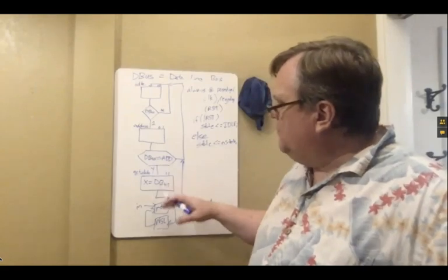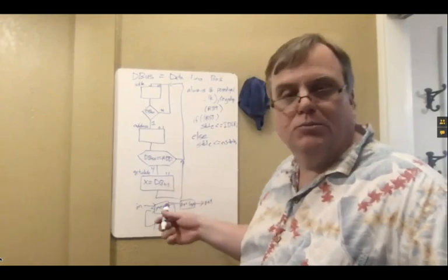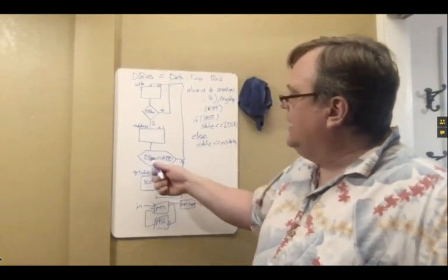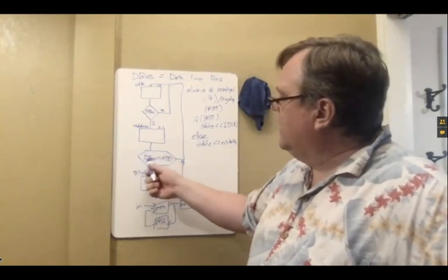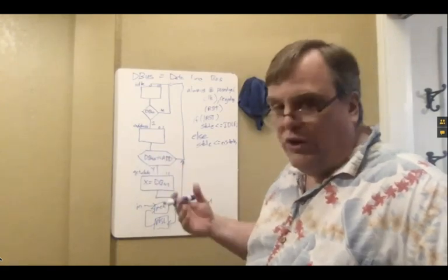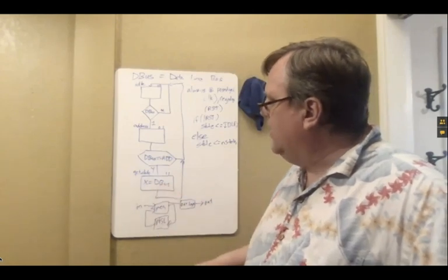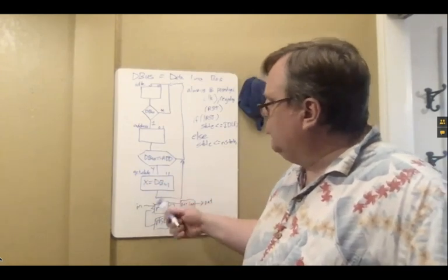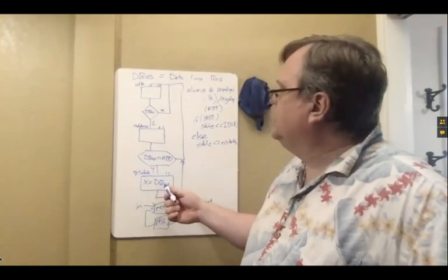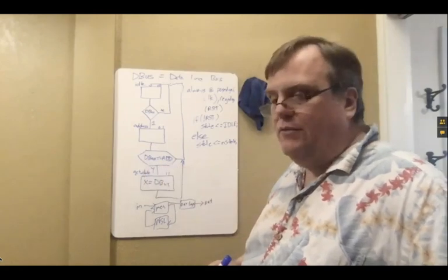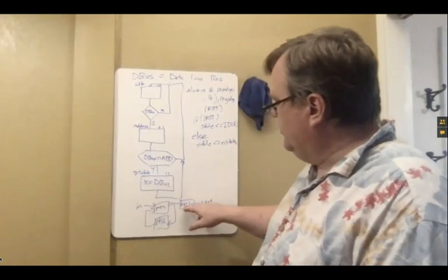Remember, if you've got output logic, you really should never read it, i.e. it should never be on the right-hand side of an expression. It should only be on the left-hand side. Everything inside a decision block, both left and right, are reads, so I should only have writes. So it should only be on the left-hand side for an output of either a state or a conditional block. It should never be on the right of a state or conditional, and it should never be on either side of a decision. In this case, it's only on the left, so I'm good. So I don't need to do anything special here.